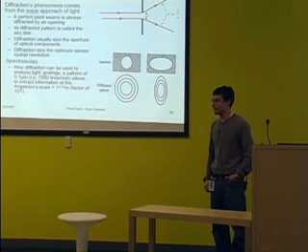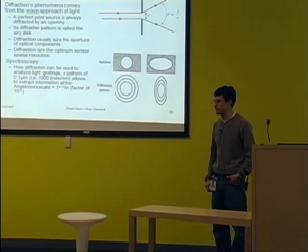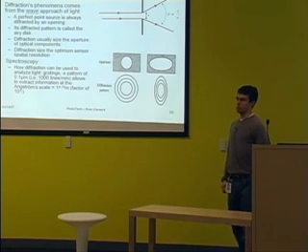In time series analysis, we run into a similar thing we call windowing in that context. And we reduce the side lobes, which I guess are analogous to your diffraction ringing, by center weighting the signal, by applying a window to the signal that weights the center more than the edges, and that reduces these side lobes. Do you do a similar thing in optics? Is there an analogy there?